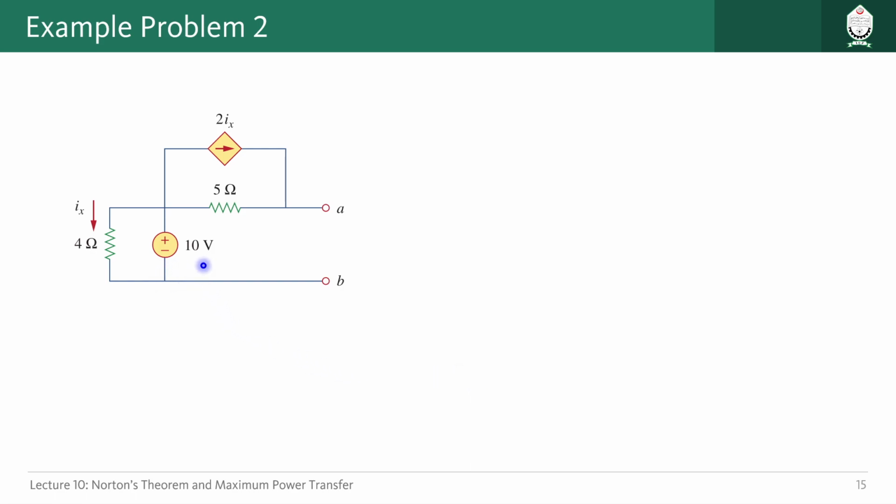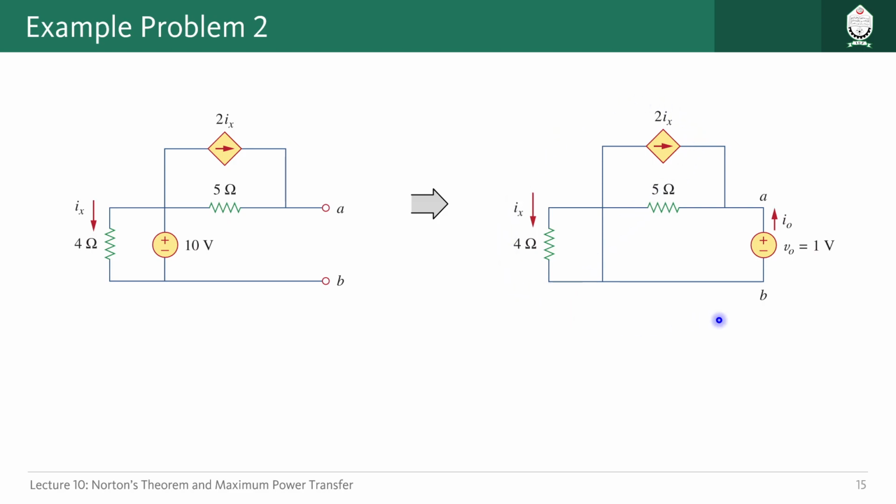So we have this independent source here, we can remove that, no problem. So this will be just short circuited, right? But for the dependent source we have here, we cannot do anything, it should be kept as it is. Then we will try to find out the equivalent resistance, right? So that is the equivalent circuit we have here. This thing is short circuited in here. Then another thing is,